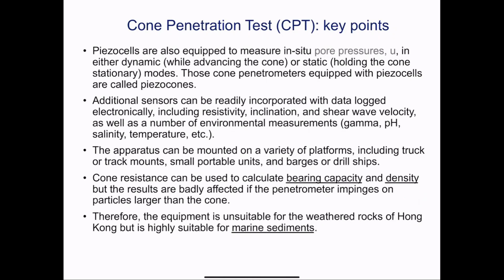Other important points that I want to bring up: there are different names for CPT. If they can be used to measure pore pressure, you might see them called piezo cells as well. Some CPTs that measure pore pressure are also called CPTU. The U is, of course, for pore pressure. The presence of pore pressure measurement is quite useful.